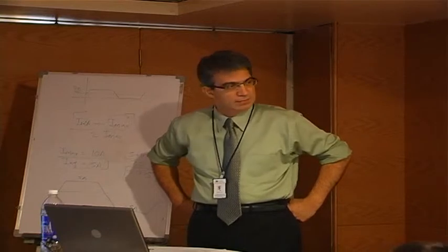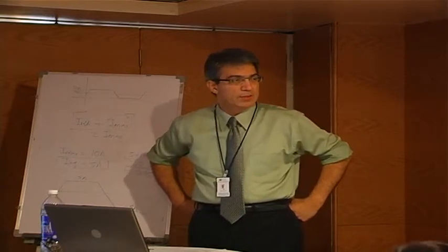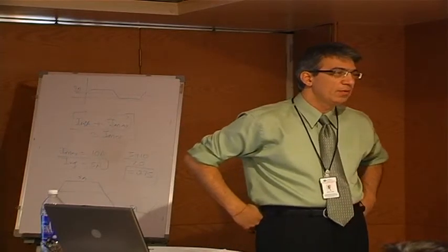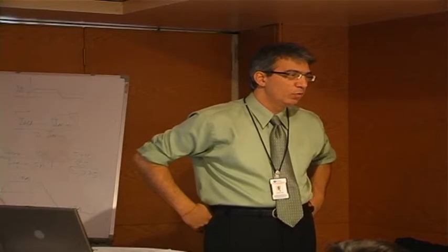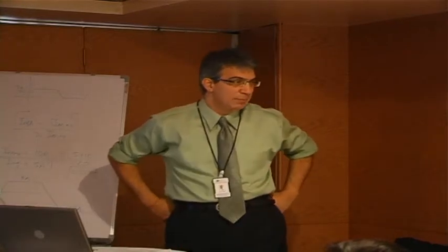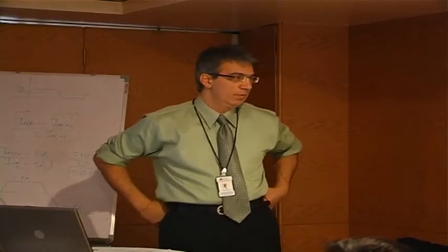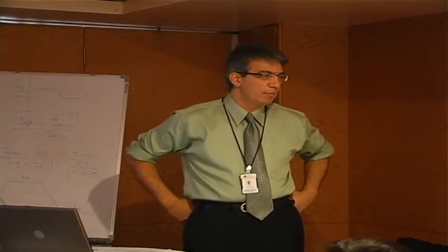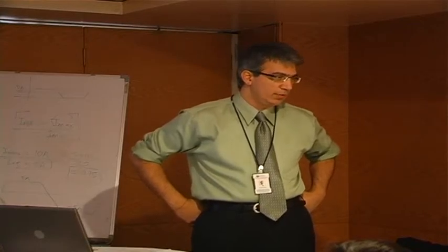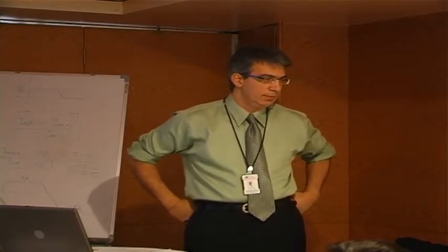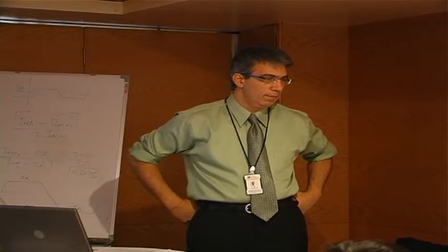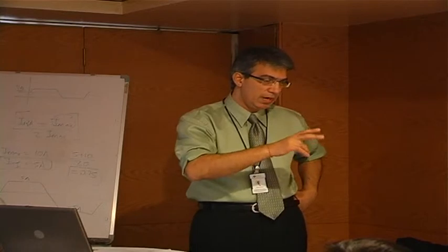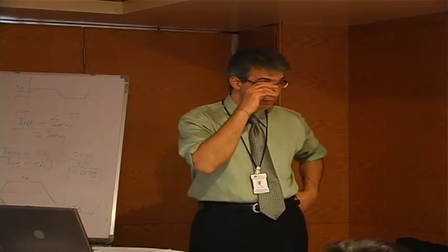How did you determine the value as 10? Arbitrary. Random values here. For example, when you're designing an inverter, you design an inverter for 60 amps, but you may limit internally to 40 amps. So Imax is sort of arbitrary. Now, we should have paid more attention to the motor characteristics here. Maybe that would have given us better results in terms of current and speed, because this is not a high power motor, this is a low power motor.